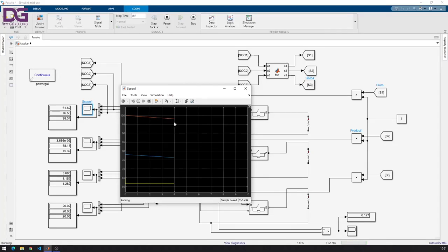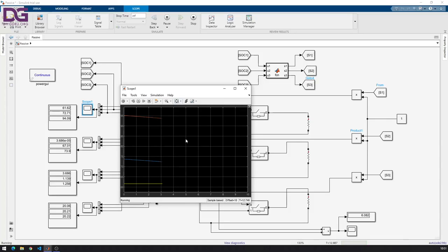See, these two are starting at a different level. And now the red one and the blue one, they are just dropping their SOC. They are trying to maintain the SOC of the lowest cell, which is about 60 approx. Right?